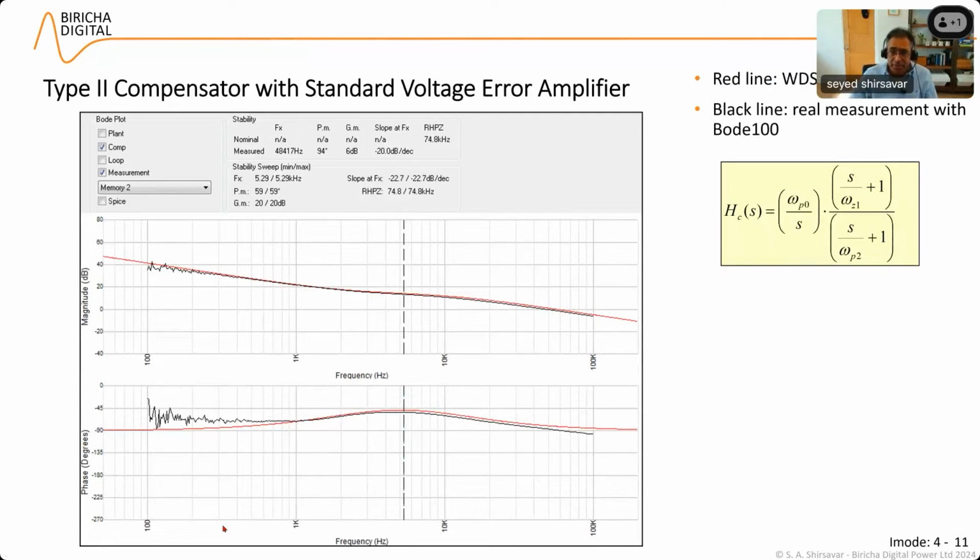Okay. And then this is the Bode plot of that compensator. I'm going to get it right this time, right? Okay, so this is my pole at origin. That is giving me this high gain, which is rolling off, right? And I've got a 90-degree phase loss. That's the result of this pole at origin. Then I'm going to hit my zero, which is up here, not down there. So this is my zero, and a zero flattens the gain by 20 dB, a right-hand plane zero, and gives you a phase boost of 90 degrees.